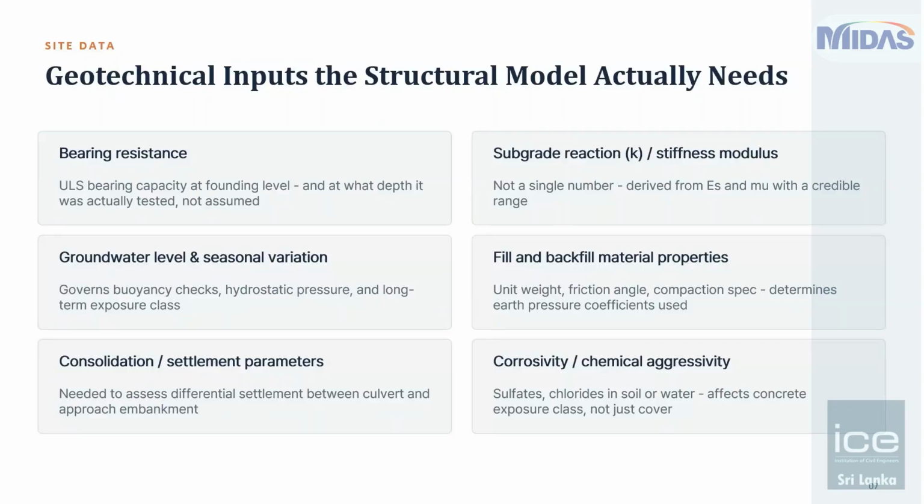Generally, as a structural engineer in a structural model, we do not exactly model the bearing capacity of the soil. We model it as springs, which will have a subgrade stiffness. The input of subgrade stiffness is generally provided by the geotechnical team. However, there are standard textbooks which can derive the subgrade stiffnesses for you using empirical methods. Bowles' book is quite well known in the industry for such estimates of soil subgrade modulus based on simple SPT values and plate load tests.